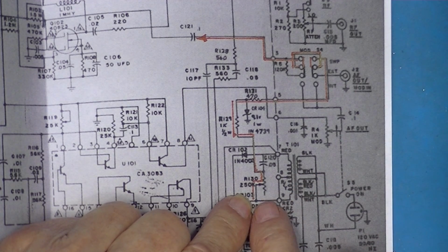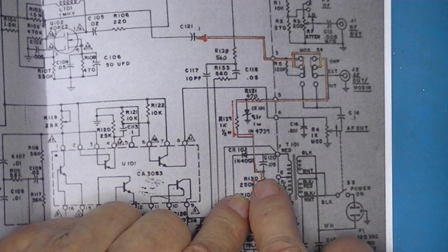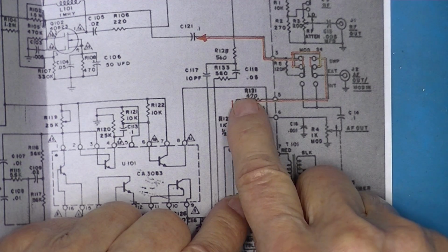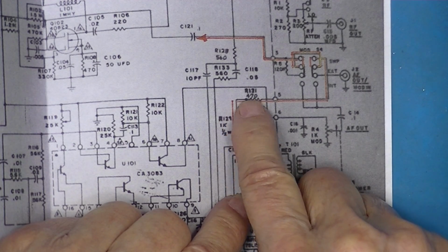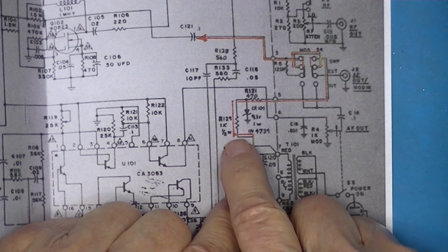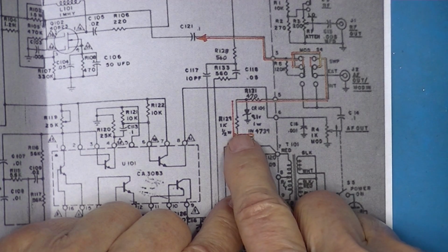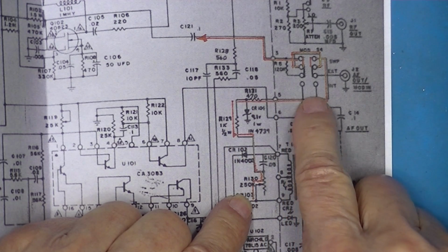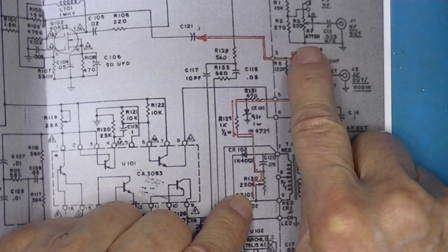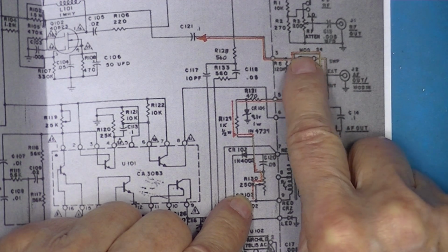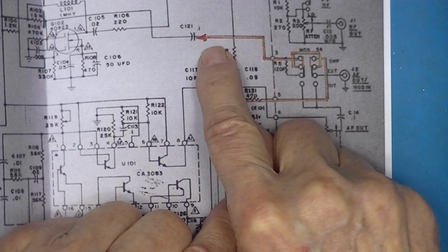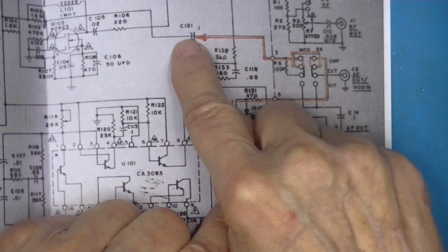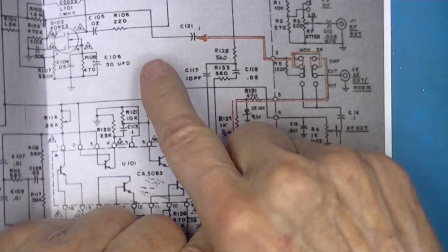Some 60 hertz signal is tapped off here through a potentiometer, up here, through a wave shaping circuit, a 1K resistor, a Zener diode, out here, up here, and does a little round the ring, comes out here and is applied to this capacitor and continues on its way to make an AM modulated signal.